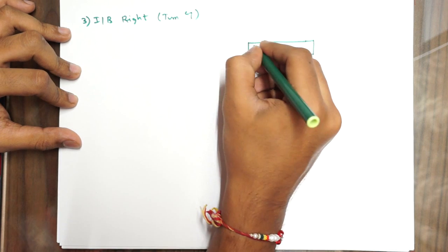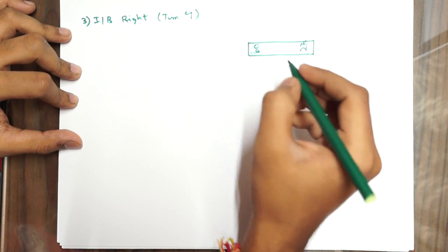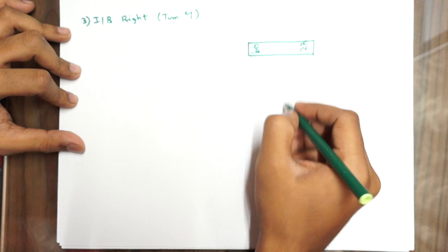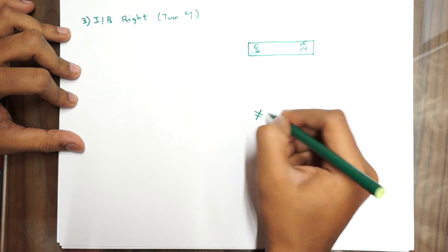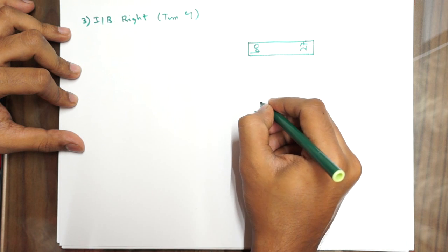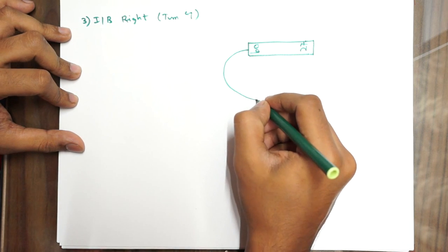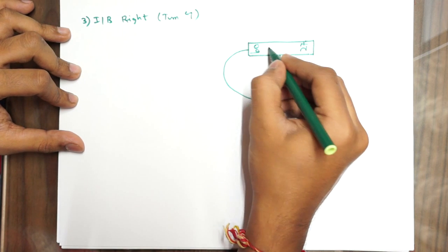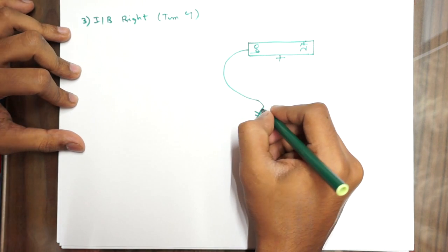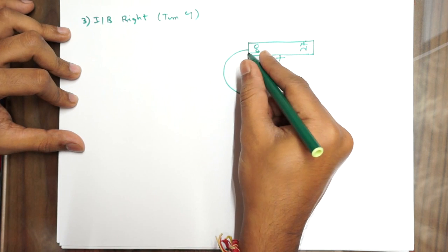For understanding purposes again, same runway. Okay, now you're coming in to land on 09 and you are somewhere here. Okay, so we have been asked to establish an arc, something like this. It's not really a good arc, but whatever. So this is your VOR and you're supposed to land here. As you can see, this turn is the left turn, and then it's a right arc.